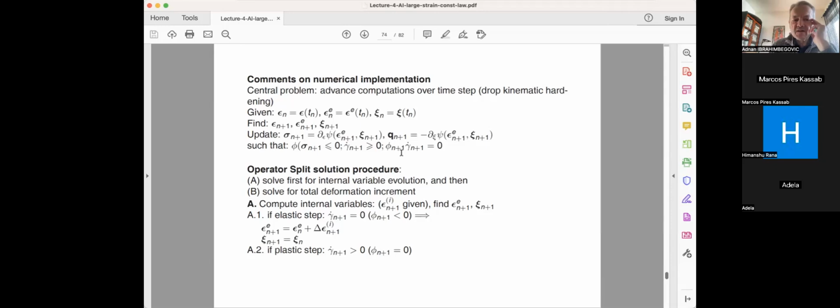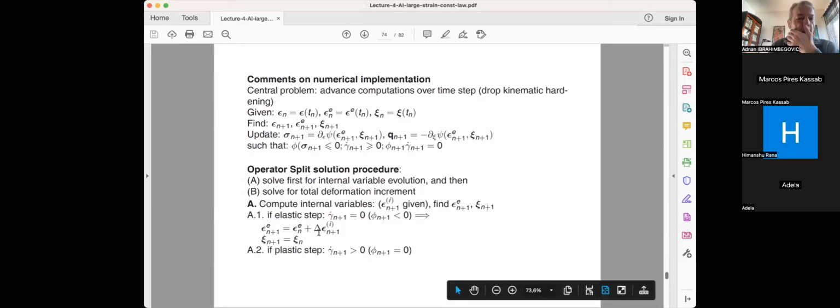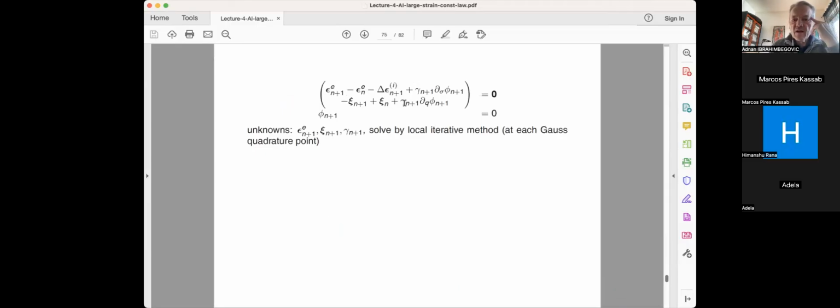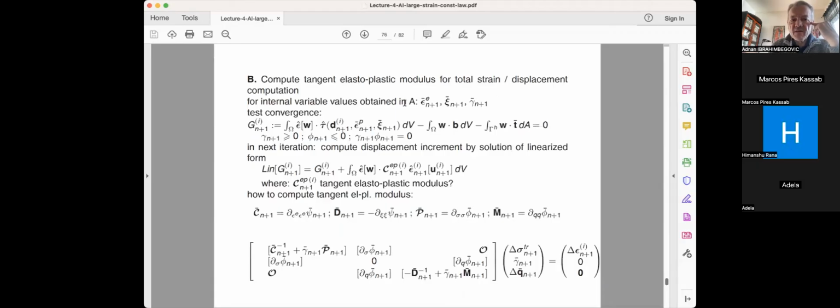So I go back here to plasticity. Really the step is that when you do this elastic trial step, you get the corresponding update, and then you have to do the corresponding modification for the plastic part. This type of computation is done independently for each and every Gauss point of the elements which have plastified. I will also need to compute the plastic tangent modulus.